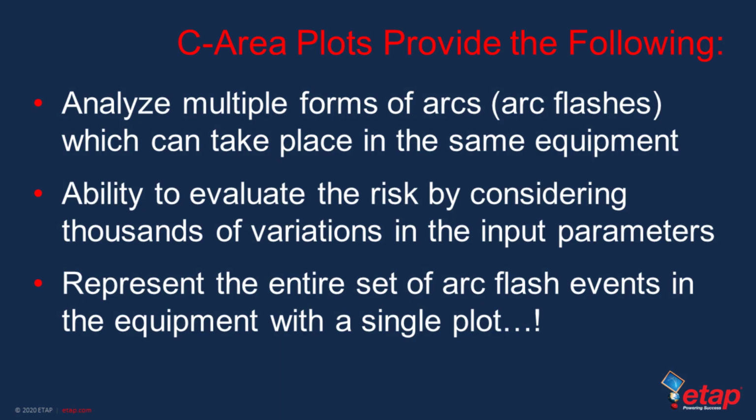The C area plot by itself allows us to analyze multiple forms of the arc or the arc flash, depending on the amount of current. An arc could become an arc flash without having to switch the input parameters to multiple combinations. In reality, an arc inside any piece of equipment can take on multiple forms.